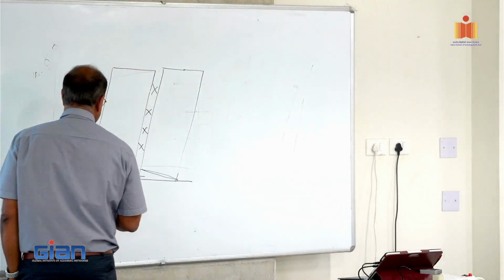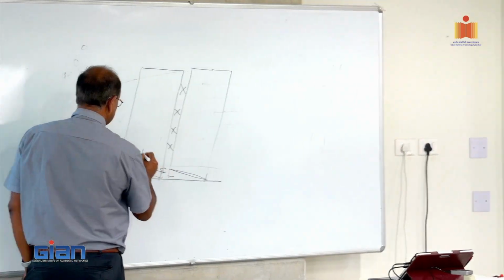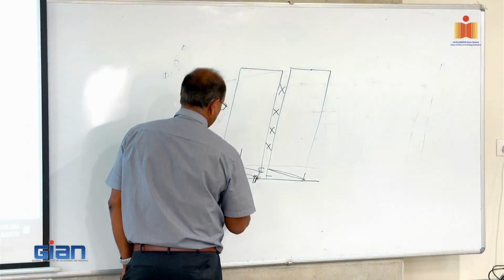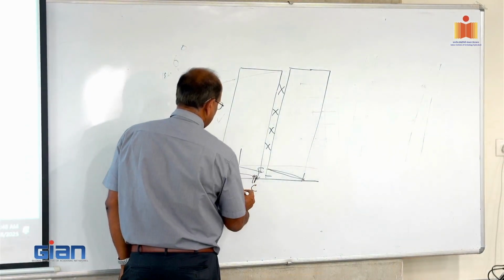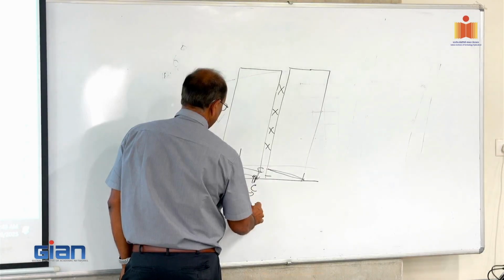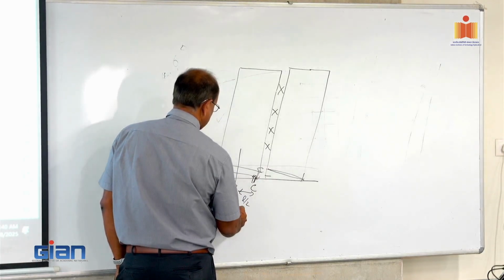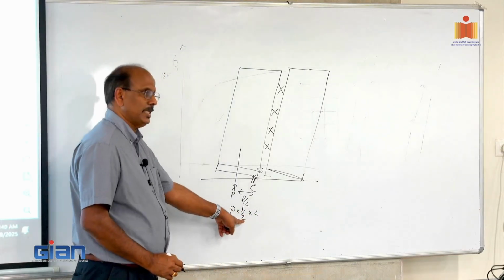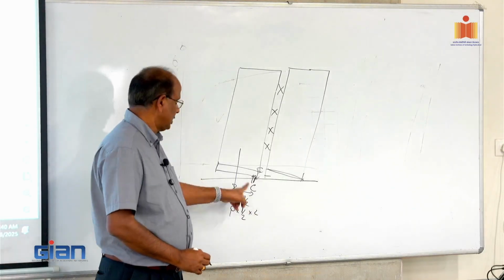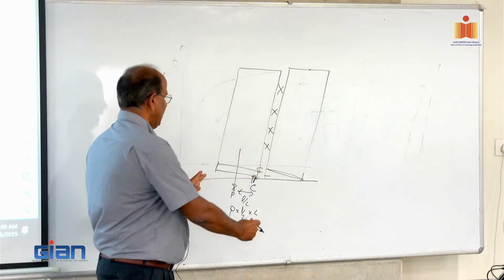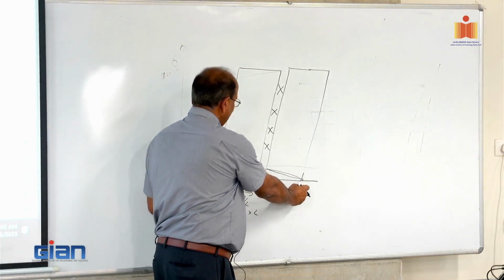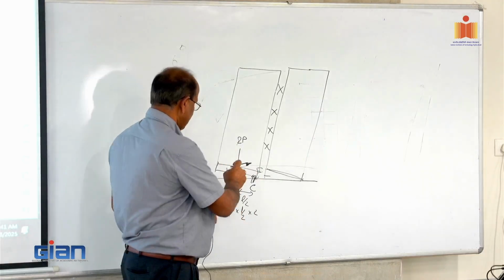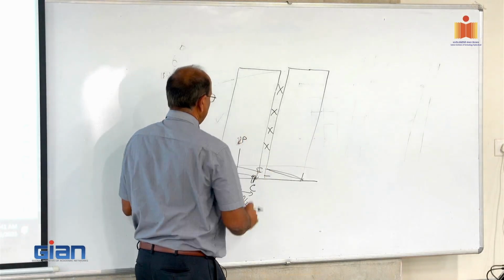Let's forget the connectors. I have post-tensioning here, here's the compression. Let's assume this is L/2 roughly. So my moment capacity is P times L/2, and you have 2 walls, so you get P times L. It's the moment resistance for the entire system. If it's just 1 wall, then I would have 2P here, or say 1P here and 1P there, because you couldn't concentrate it.